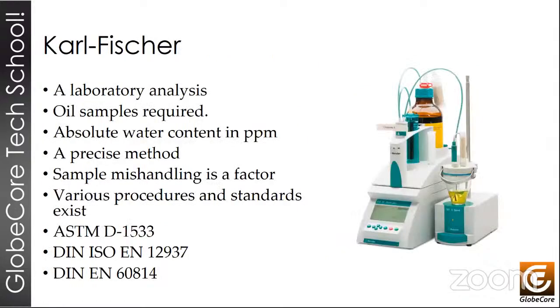Right, so the Karl Fischer is a titration method for quantifying the water content of liquids and solids. It's one of the most commonly used measurement methods today. A sample is dissolved or suspended in a suitable solvent free of water, which would usually be dry methanol, and an iodine reagent is added with an automatic portioning device.